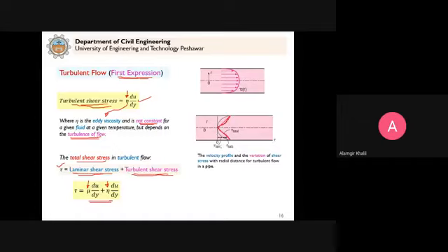Now in this case, you see that near the pipe wall, we have a viscous sublayer that we discussed before, and I will discuss how to calculate its thickness in the coming slides. So even if we have turbulent flow, near the pipe wall we have a laminar-like condition. It's not true laminar flow. Remember, it's not true laminar flow. It is written in the textbook. You read it.